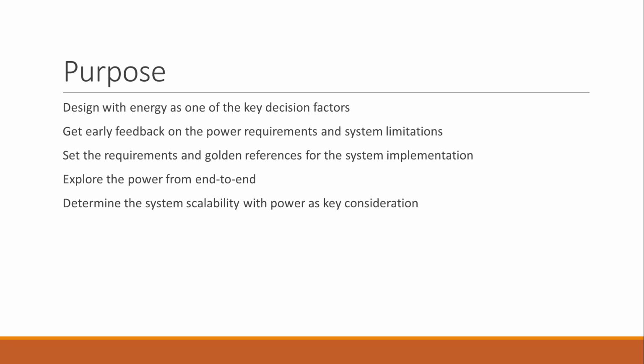You want to look at really end-to-end power, depending on what your design is. If you're doing, say, a space system, you want to look at your photovoltaic cells, your batteries, all the way up to your management when you have an eclipse. The other aspect which is very, very important is your scalability. You have a system you built, you have certain applications, but what happens in the future when you want to add more applications? How does it impact your power?